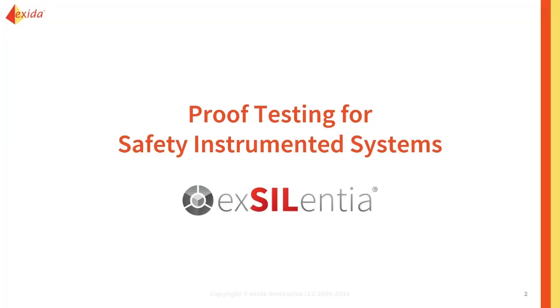Hi, everyone. Thank you so much for joining me today to talk about proof testing for safety instrumented systems. We'll discuss how we work through the functional safety lifecycle to determine proof test parameters that are part of our design calculation, and ultimately create a proof test that we can carry out on site to make sure that our SIF devices are functional and able to respond to a hazardous scenario. We'll also talk about the data that we collect during the O&M phase to ensure that on-site we're meeting our safety integrity requirements.